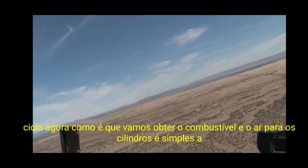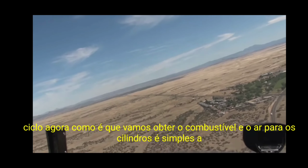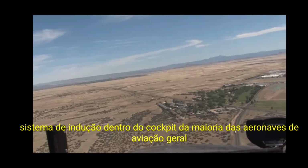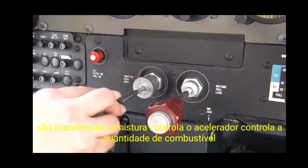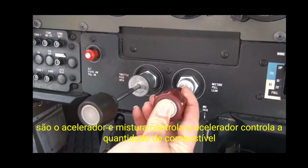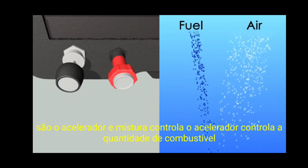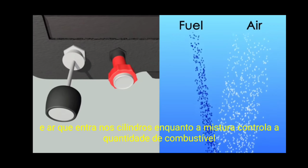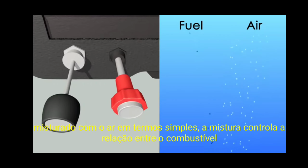Now, how do we get the fuel and air into the cylinders? It's simple. The induction system. Inside of the cockpit of most general aviation aircraft, there are the throttle and mixture controls. The throttle controls the amount of fuel and air that go into the cylinders, while the mixture controls how much fuel is mixed with the air.